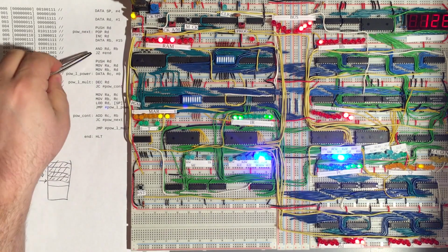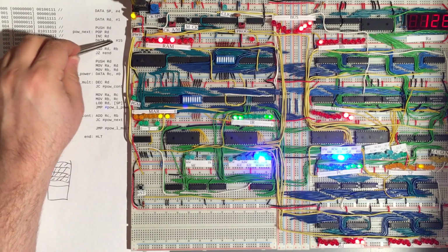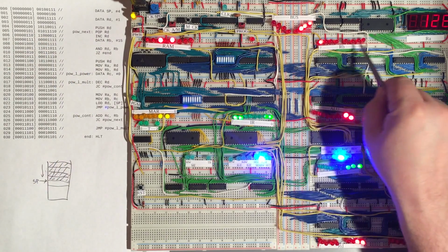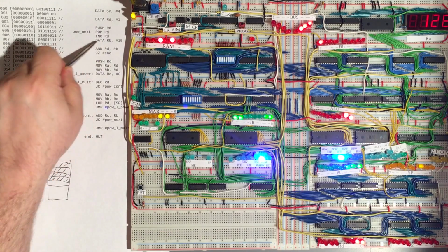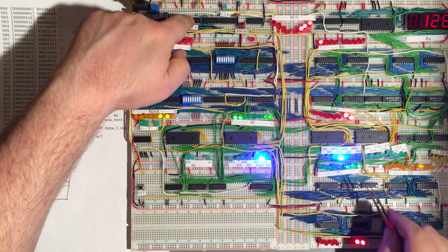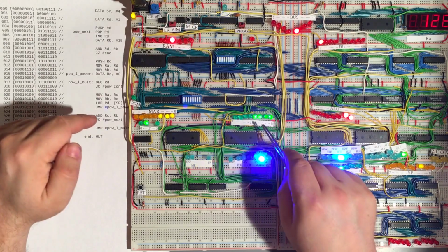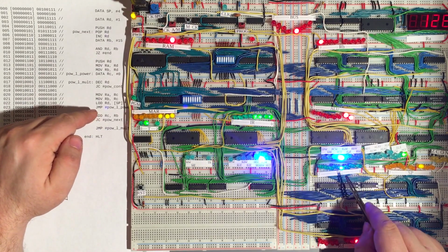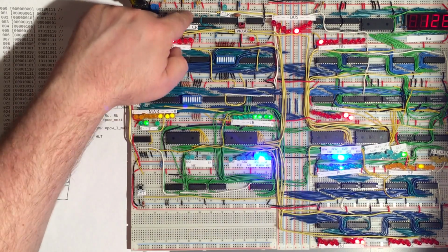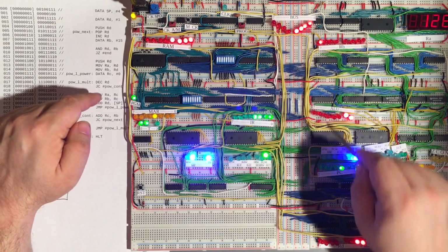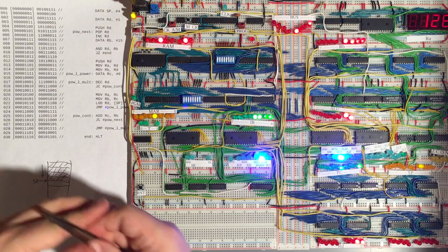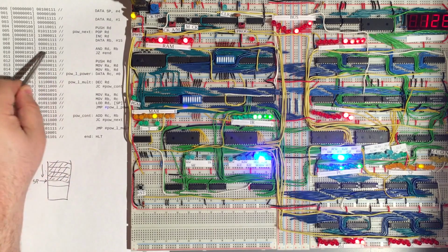And so then we have a data instruction here. We're going to load this B register with a fixed value of 15, and we'll see in just a moment why we're doing that. So let's just go through that very quickly. So load the instruction, there it is, and so then we need to put the program counter into the memory address register again to get that 15 from program memory, and then write that into the B register. So there that is. And so now we're ready for this next ALU operation, which is an AND.